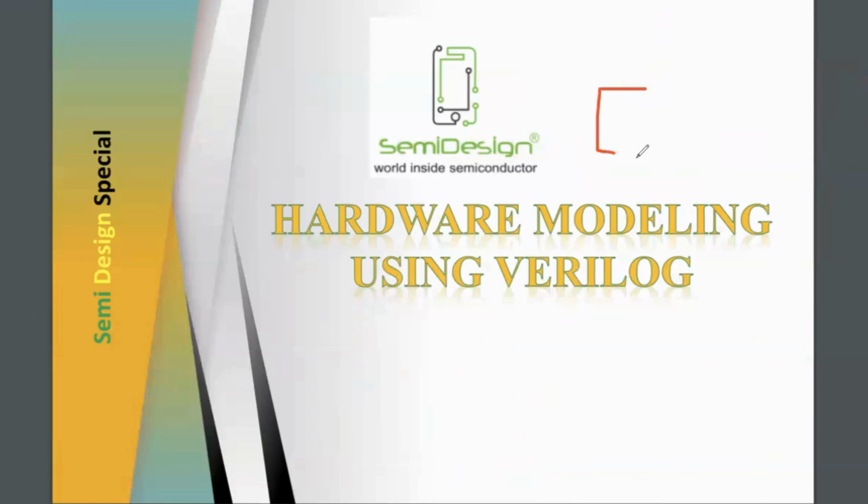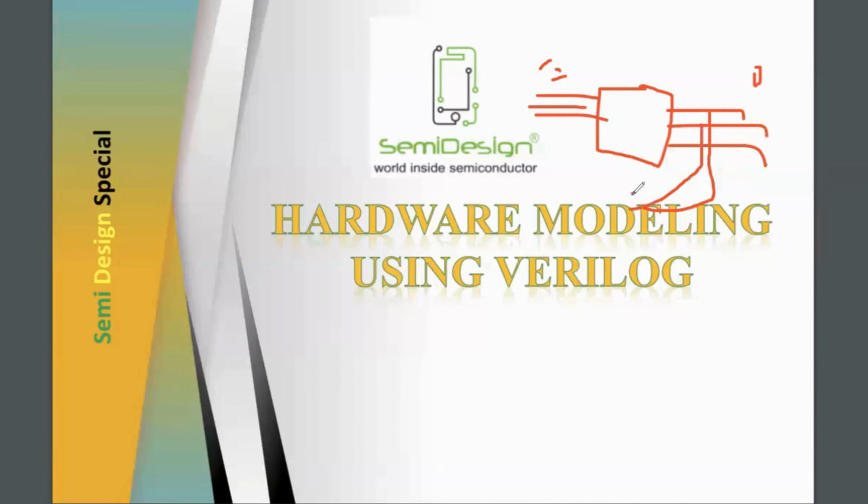When no feedback is present, it is combinational, and when feedback is present, it is sequential. Okay, so combinational means whatever input we apply, we get the output for that. But sequential means we will have the memory element. This memory element will be connected in a feedback to the combinational logic circuit, so that the previous output will be stored in this memory and sent to the next input. That's why we say this total circuit is a sequential logic circuit which stores the data.